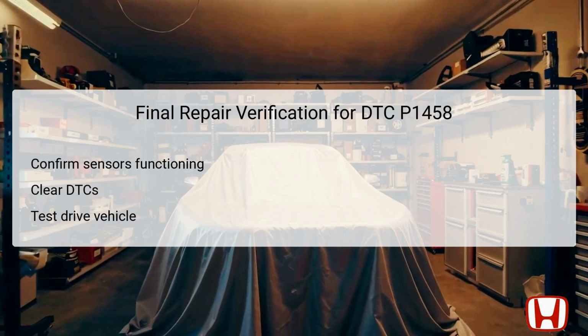Upon completing the necessary repairs and replacements for DTC P1458, it is crucial to undertake a final verification step. This step involves confirming that all related sensors are functioning correctly and that any parts replaced, such as the FTP sensor or the evap canister vent shut valve, are operational. Following this confirmation, a diagnostic scanner should be used to clear any diagnostic trouble codes, DTCs, that may have been logged during the testing process.